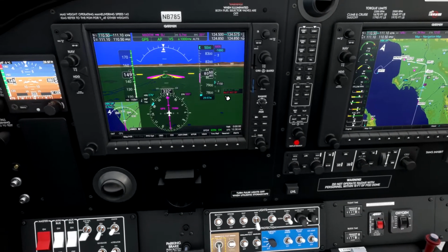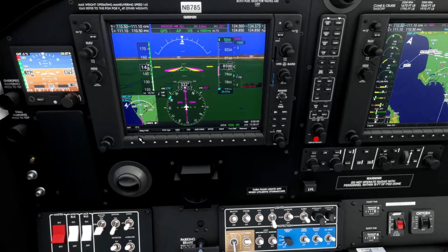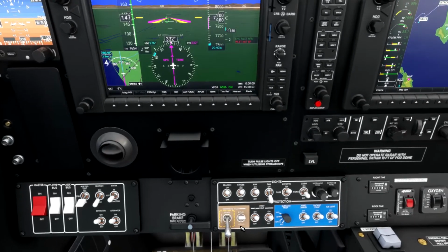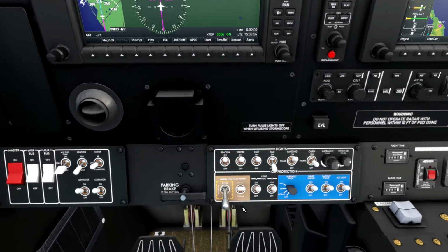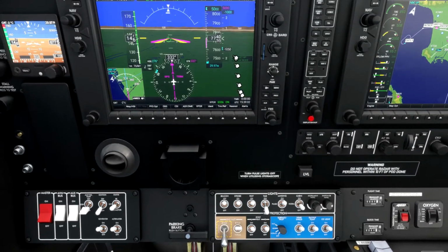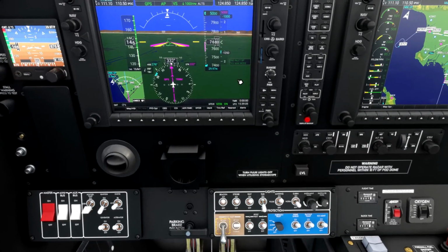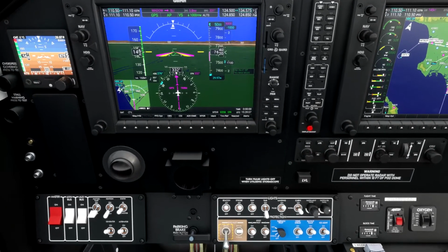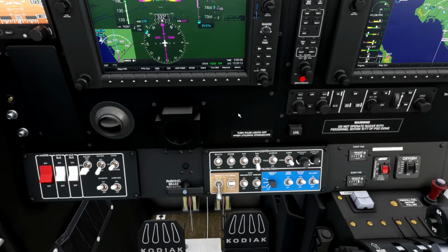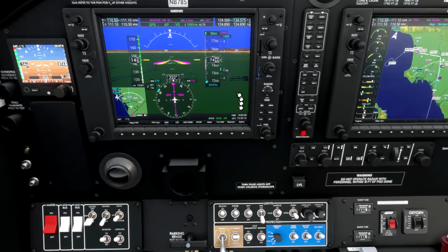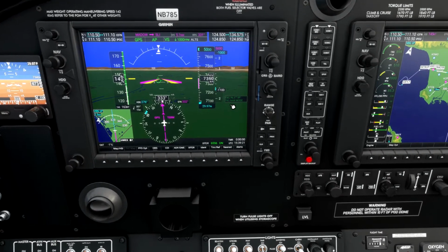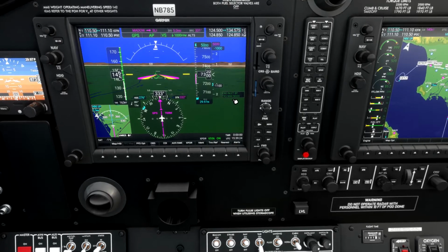This icon is about an inlet to the airplane, and when it's very cold and you're in rainy weather, you want that inlet closed or bypassed. When you first turn this up to bypass, it doesn't automatically clear that out. It takes a few minutes. I'm not exactly sure what's going on, but my guess is that it just takes a few minutes for that bypass to take effect, and once it does, then it changes to give this information, TKS max mode.